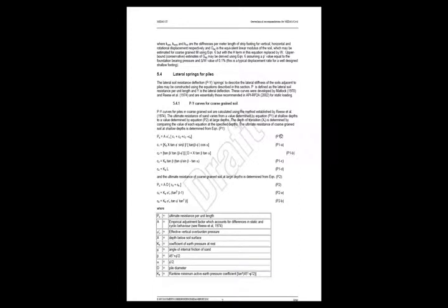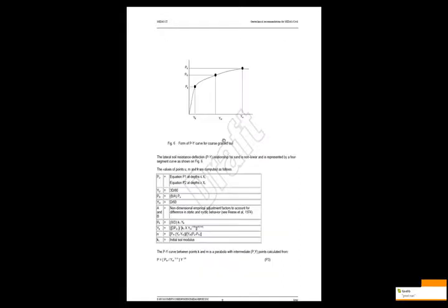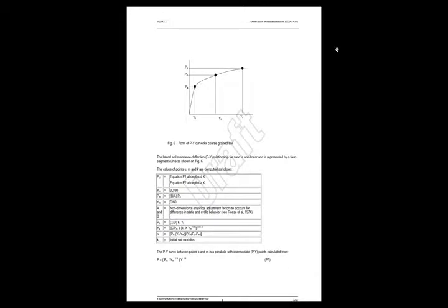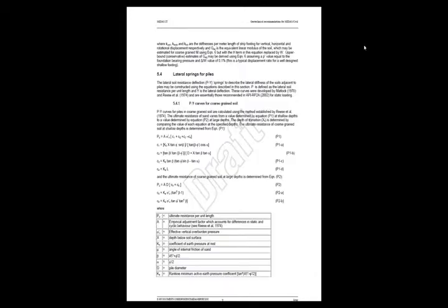Okay, here we are. The answer to Grant's question, what is the basis of built-in soil properties used in the integral bridge support menu? It is based on Matlock and Reese, and this is how the PY curves are generated. It's a very standard approach that is generally used by geotechnical engineers to obtain the soil spring supports, and structural engineers also use this approach. And this is how Midas Civil generates the spring supports when you use the integral bridge supports.